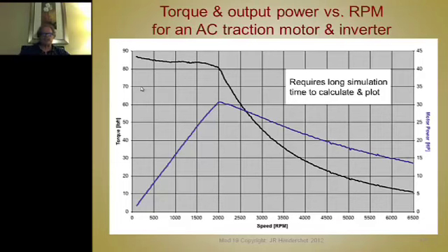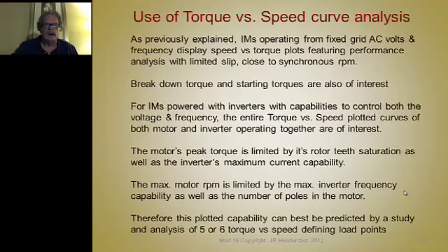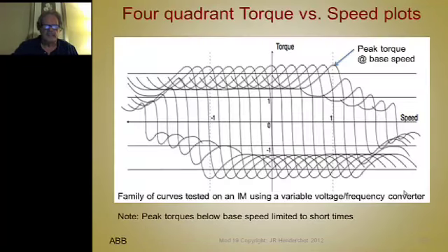There are many applications that now require an operating envelope. Here's a requirement for a torque speed performance curve of a motor that has to have a constant torque range for a vehicle traction, for example, and then a constant power range. So how do you define the capabilities of the motor you've designed to fit in that envelope? Certainly that black plot has to fit inside this envelope.